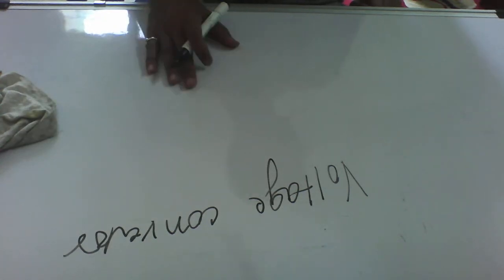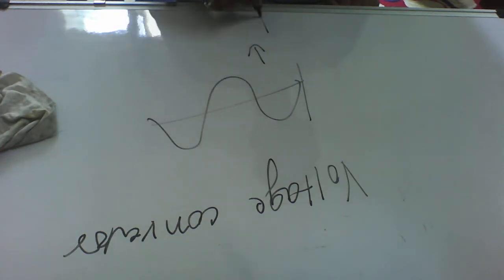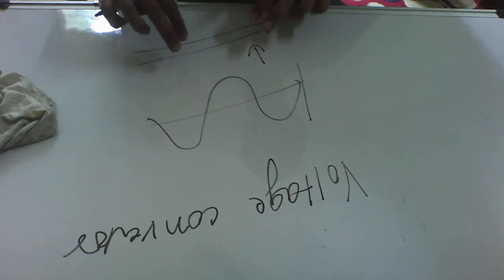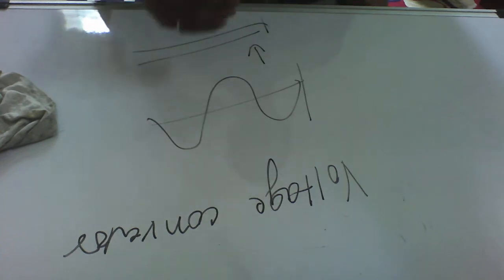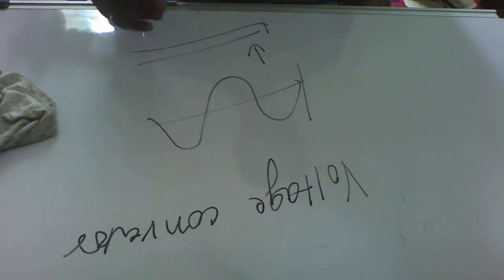For a DC output, the AC input is rectified, and that DC output is shifted by a shifter circuit that can be used to produce different magnitudes of DC level. For output voltages above 10 volt, ordinary silicon diodes are used.